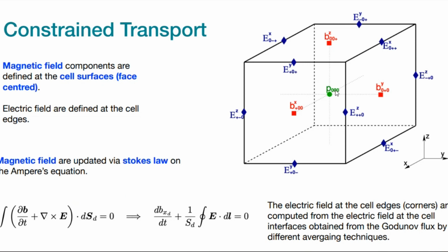So if you are computing this part, actually we do not have a boundary condition. We evaluate one side just from the divergence-free criterion. So you find the cell averages on all sides and evaluate that from the divergence-free condition. This becomes problematic if you have non-standard boundary conditions. Okay, you'll understand this more as you work on it. So I will stop here. Any further questions? Otherwise, we'll go further.